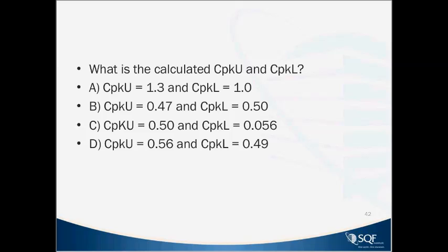Obviously, we saw from the histogram before that there was a lot of stuff on the lower side that was out of spec, and obviously a very low CPK number does that. But similarly, if they had a spec, in this case of 19 ounces, there was lots of stuff going on there too. So the number that you get should align with the histogram picture.